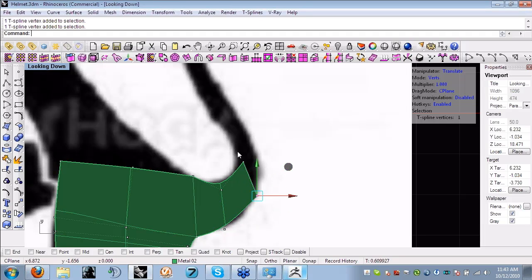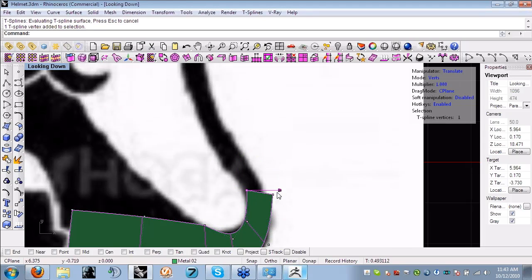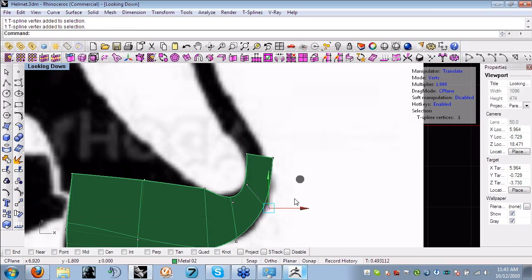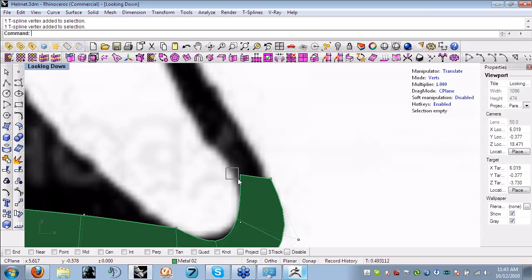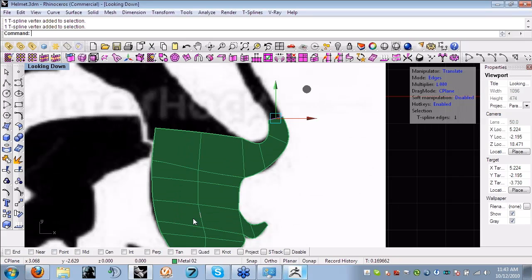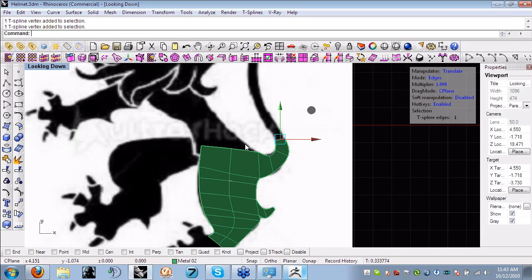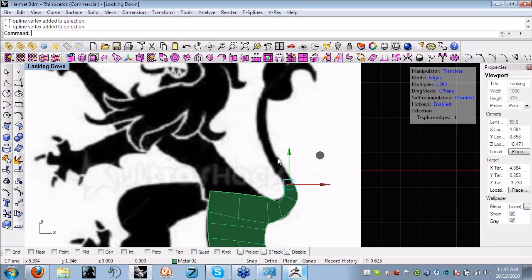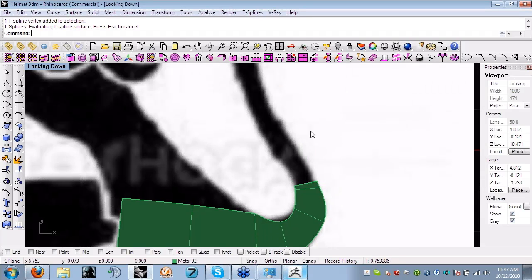And there's just another question that came in about how when you're doing this with the line, if you just traced an outline and then thickened it, and the answer is no, you need to do a little bit more than just outline it. You are actually kind of creating the surface as you are pushing and pulling and extruding these faces. Yep, and the big thing too with the style of modeling is all of these little square and rectangle patches basically represent the topology of the model. And if I'm clicking and drawing with a curve, I may not get cross sections right here or UVs where I necessarily want them later on.